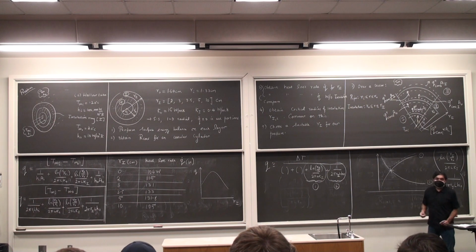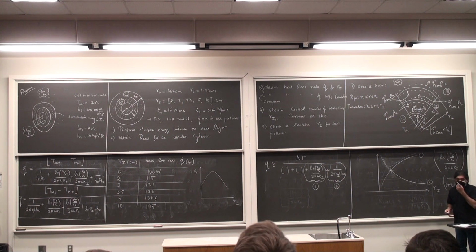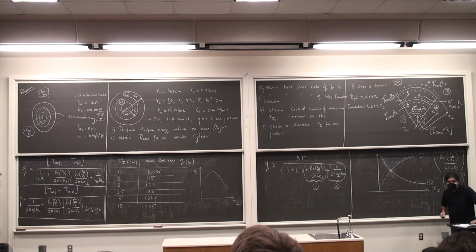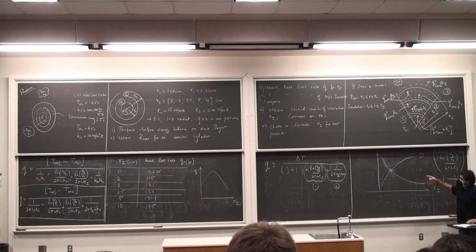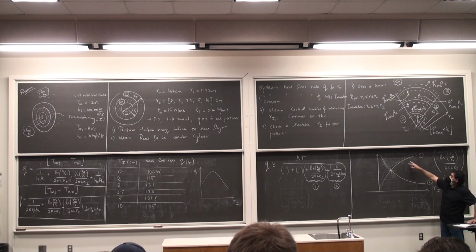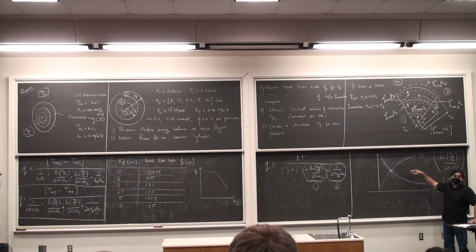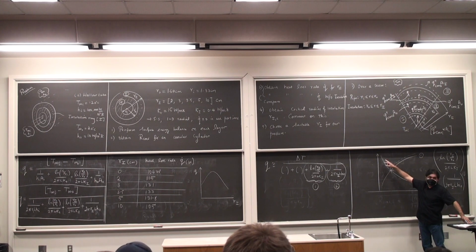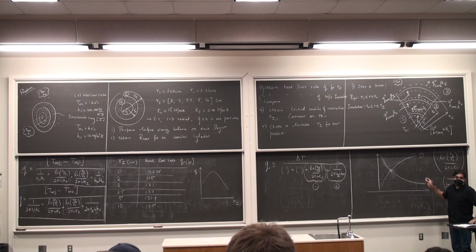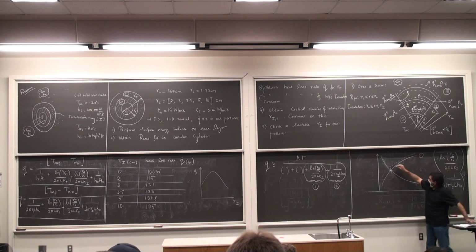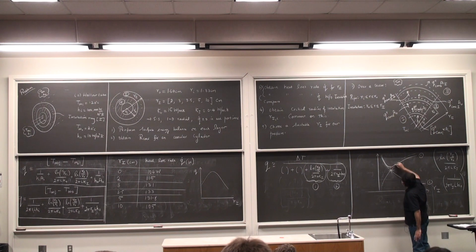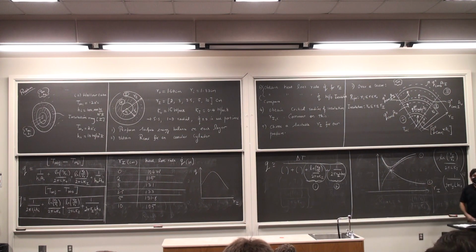Yes, sir. So when we have a certain radius, we can think of the insulation as pulling more heat than just ambient air, as far as conceptually why the heat goes up. Right. But it depends. There are two things that are at loggerheads with each other. If one is low, the other is high. If one is high, the other is low. It's a combined behavior that you need to look at. So that combined behavior is this line here, which is the sum of these two.